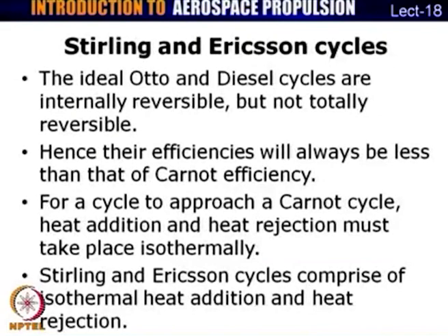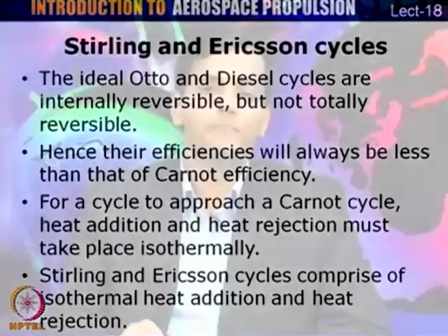Now, let us start discussion on 2 conceptual cycles which are supposed to have very high efficiencies. We already know that the ideal Otto and diesel cycles are not totally reversible. They are internally reversible, but it is possible to have irreversibilities outside the cycle, which means that ideal Otto and diesel cycles are not totally reversible. This means that the efficiency of the ideal Otto and diesel cycles can never be equal to the Carnot efficiencies, because they are not totally reversible.